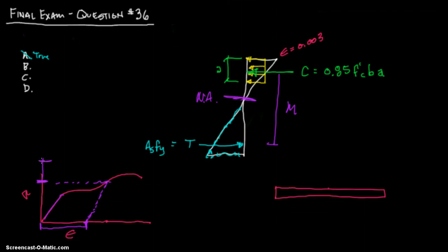Now, if you went all the way up here, obviously that's a catastrophic failure, because the steel cannot hold that. But the good property about steel is that it will start lengthening. It's something called strain hardening, and the steel actually gets stronger, and it's able to hold those higher stresses, but it had to deform so much to do it. So you take that load that overstressed it, and the beam will look like this. That's obviously pretty overstated. I doubt it's going to deflect that much, but just to show a point,